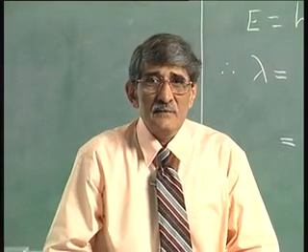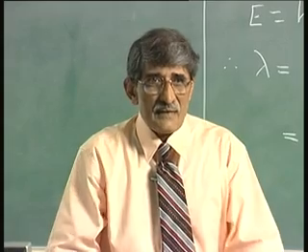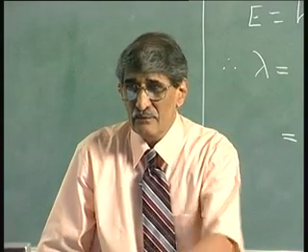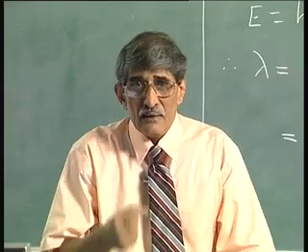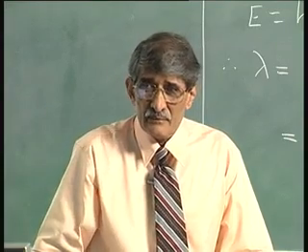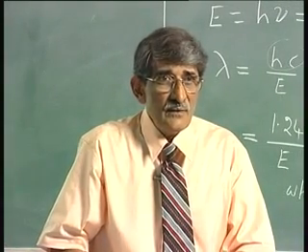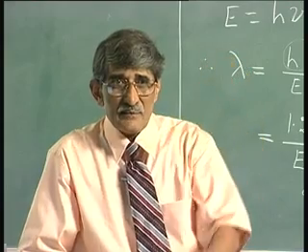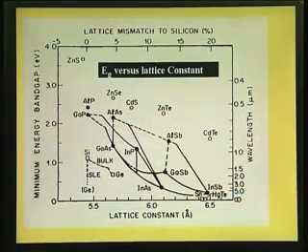You make a p-n junction, forward bias it, pump in current, that injects carriers into the, for example, if it is a n plus p diode, electrons are injected into the p region. Those electrons are minority carriers which will recombine, and when it recombines, the electrons drop from the conduction band to the valence band. So, if your energy band diagram is like this,